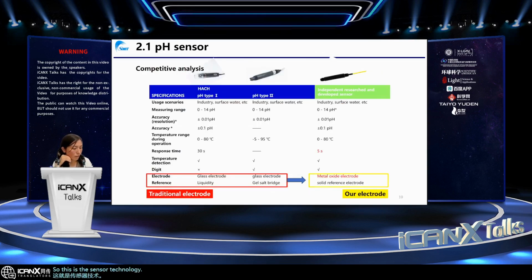For our sensor, we also compare our instrument with well-known brand products, and this is the comparative analysis. We have improved the response time from 13 seconds to 5 seconds, and our electrode is the metal oxide electrode and has a solid reference electrode.